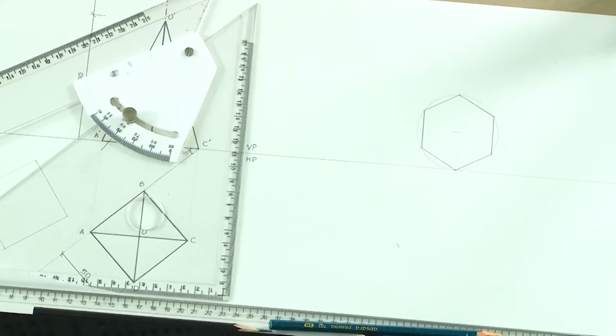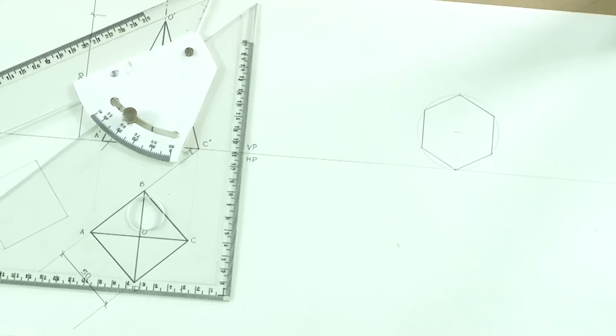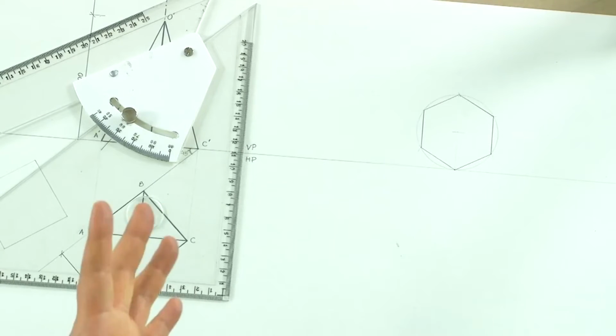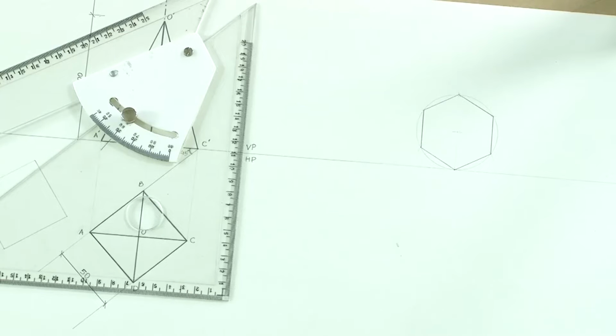So, this is the hexagonal shape based upon the condition that we have been given, that this time we are not dealing with a pyramid, we are dealing with a prism, and this prism is perpendicular to VP. So, we know that the base of this prism is going to be seen in its true shape in VP, because the base becomes parallel to VP, which is what we have drawn. This prism is resting in HP on one of its edges, one of its sides. So, that is what we have seen.